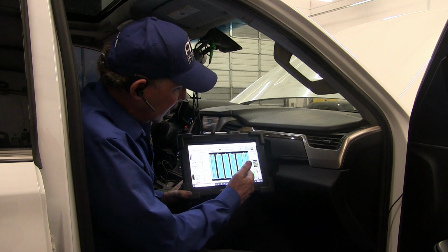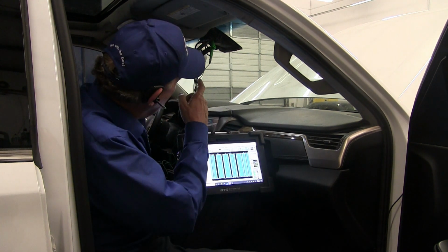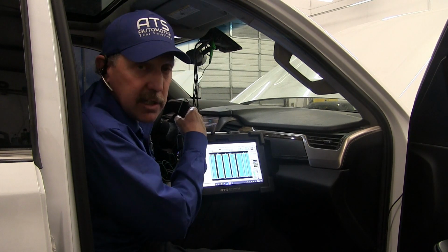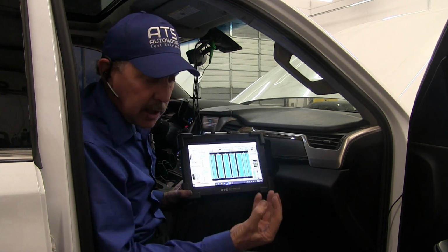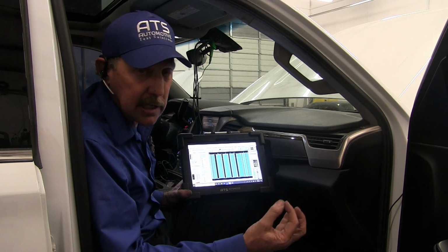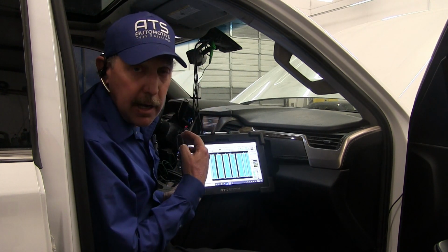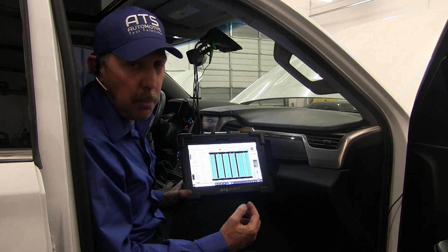These are messages that are shared on all the medium speed bus. The wire from this forward view camera is broken somewhere where it goes down to the comb. There's a comb where all these wires go together where I can disconnect each one, but somewhere between that camera and the LAN line, the bus, that wire is open.